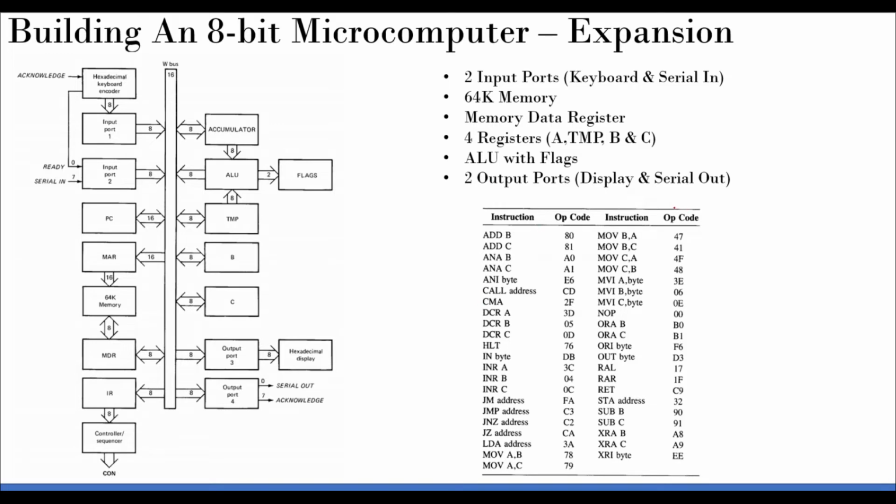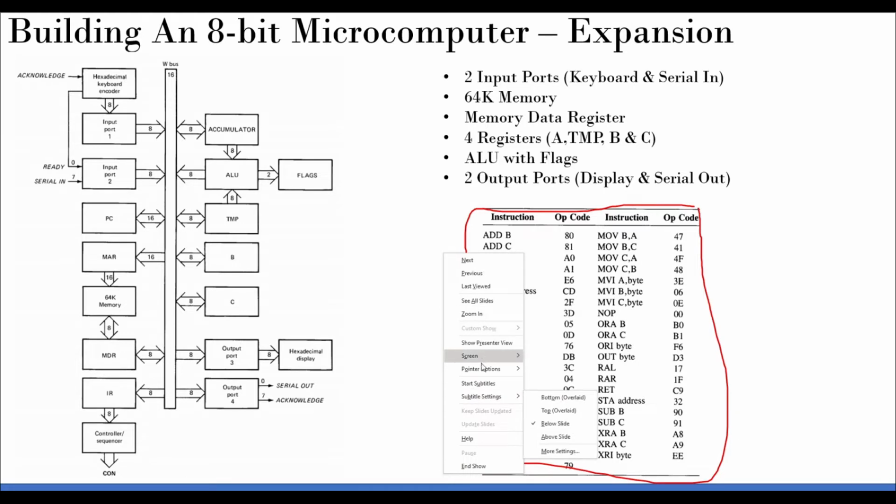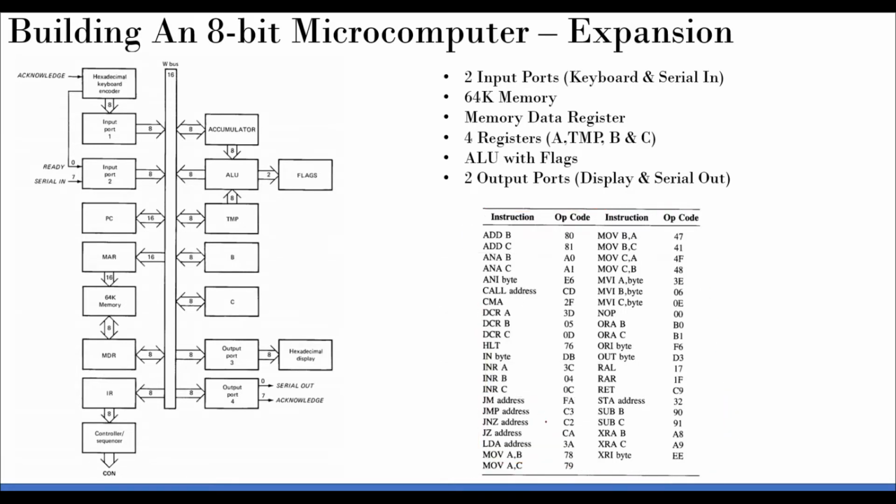And you see the instruction. Yeah, we had only add, sub, out and halt, right, in the previous. In fact, LDA, add, sub, out and halt. But now if you see here, so many instructions are there, and you are lost now, right? And you also see the opcodes. Earlier it was very simple 4-bit opcode. Now you have 4 plus 4, 8-bit opcode which is coming out.